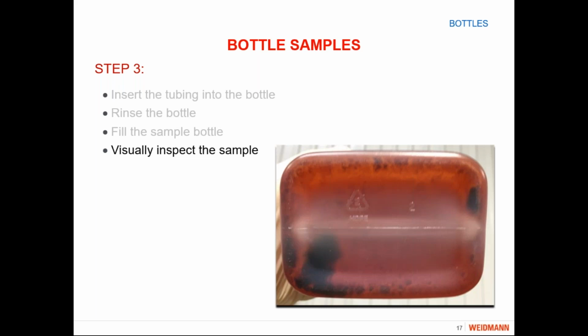And so oftentimes, if the oil is in really bad shape, if it's jet black, clearly this oil's been heavily overheated, you may get a call from the lab saying, we can't test your sample because of the quality that we got. So be aware that if it's really bad, you might want to call the lab before you send it in and say, this is what it looks like. Can you do anything with it before you send that sample in?